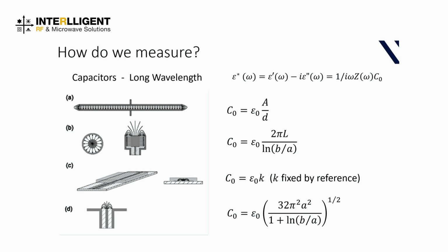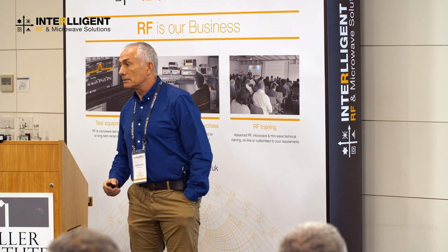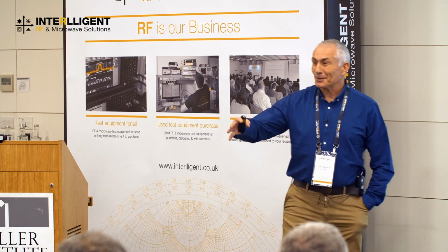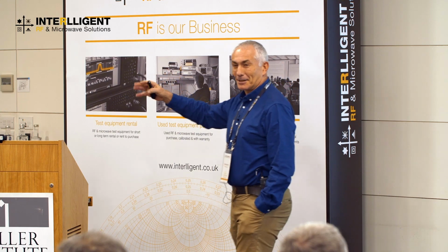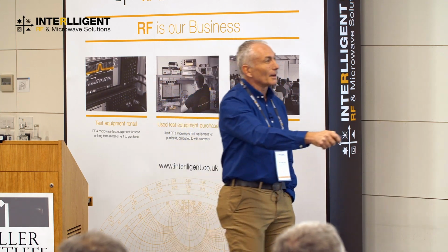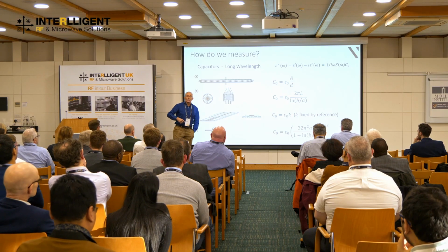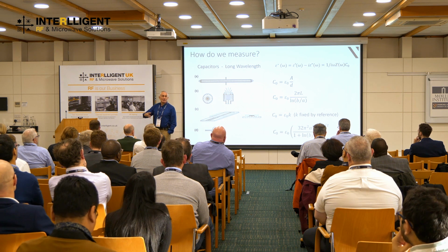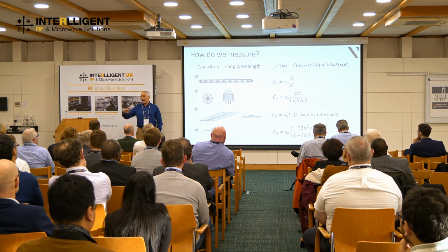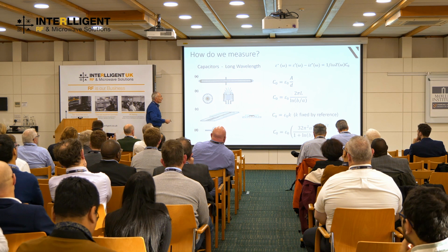It's quite simple. If you can measure the impedance, you can derive the permittivity of the material inside. Now, for most engineers, I know that the permittivity is some positive number and that's it. Not for me. It is a complex number, because it relates to the loss of energy inside that material, i.e. the action of the field on the material itself.